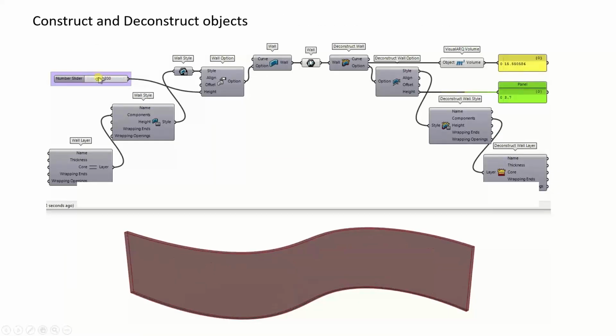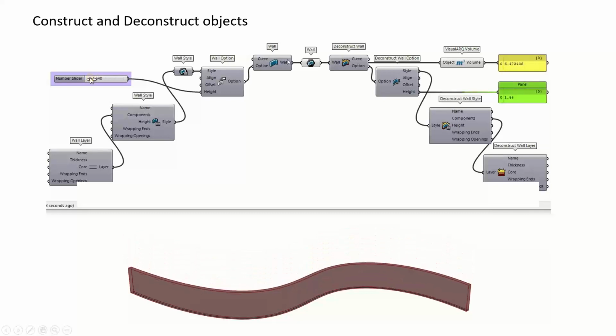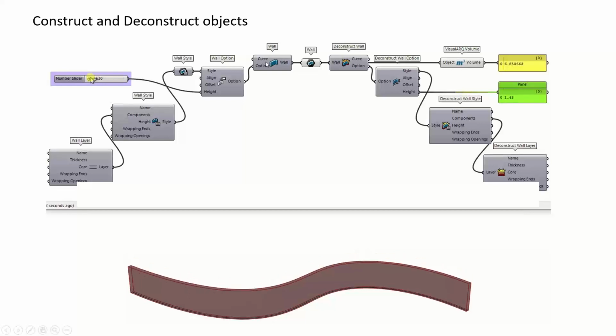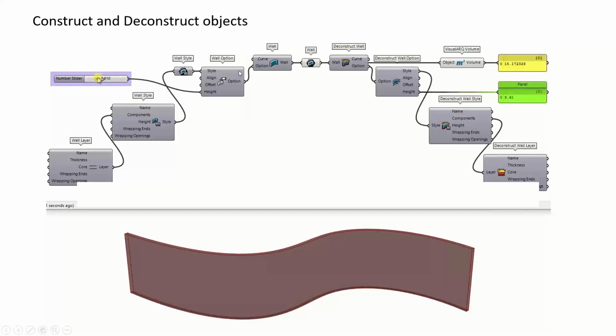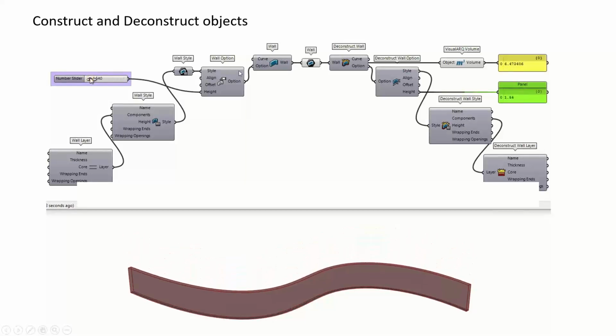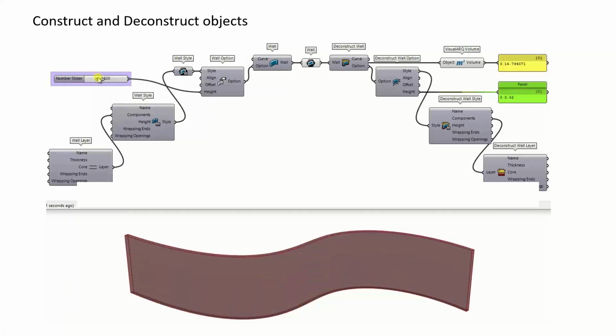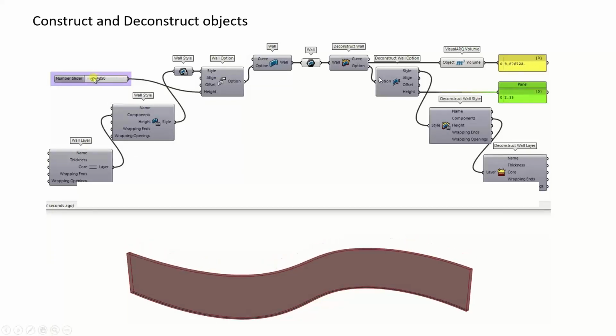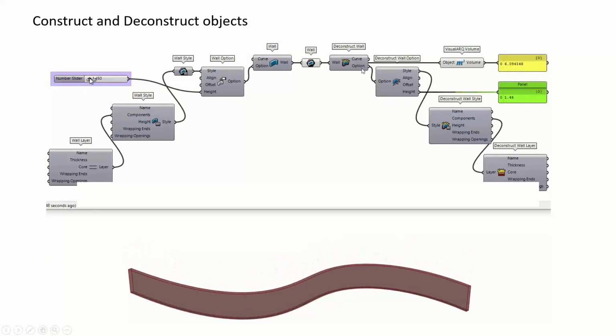So in the center, you can see a wall component, and if you look at the left, you can see a wall component that requires a path curve. Also, it has an option component to assign more details, such as the height, well, the style. We can create newer styles in Grasshopper. And on the right hand, we've got the components to deconstruct VisualARQ objects.